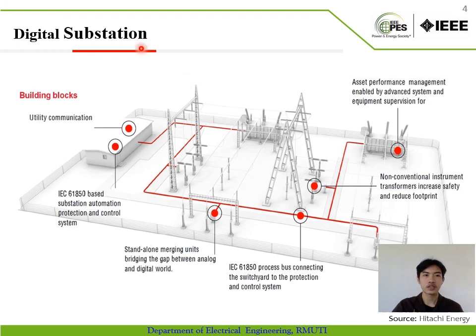This is the feature of the digital substation using a standalone merging unit that utilizes process bus input-output to collect analog current and voltage signals from instrument transformers such as CT and VT from switching equipment, and digitizes this analog signal into a digital signal over IEC 61850 to IEDs for protection and controlling the substation.